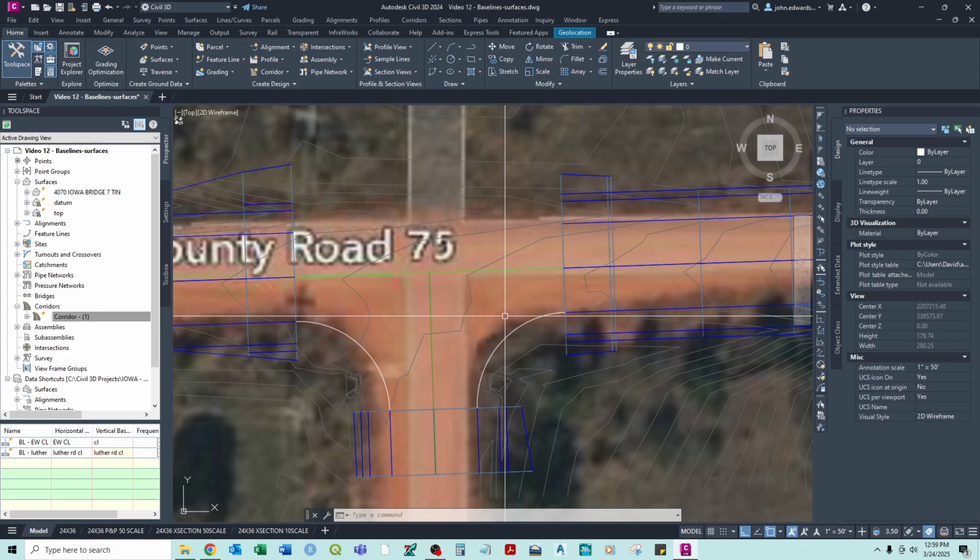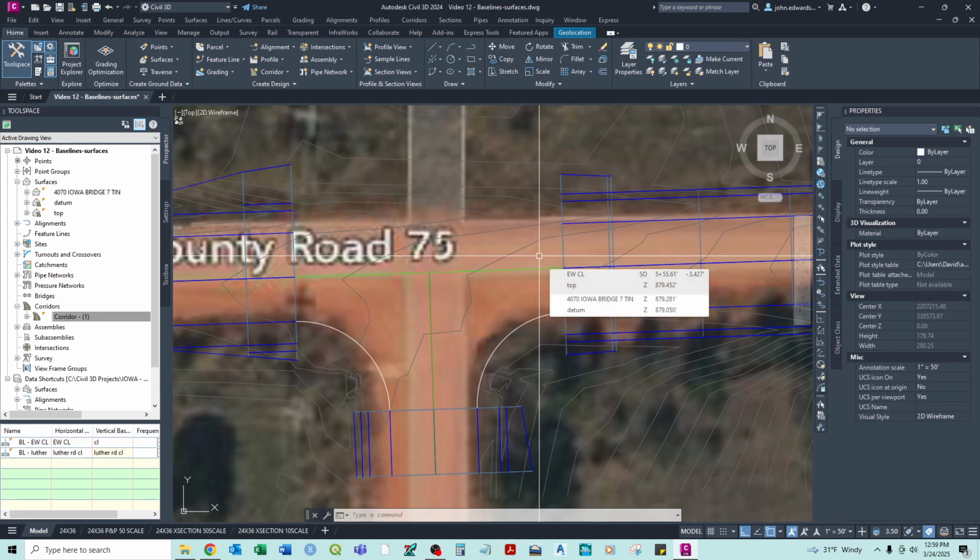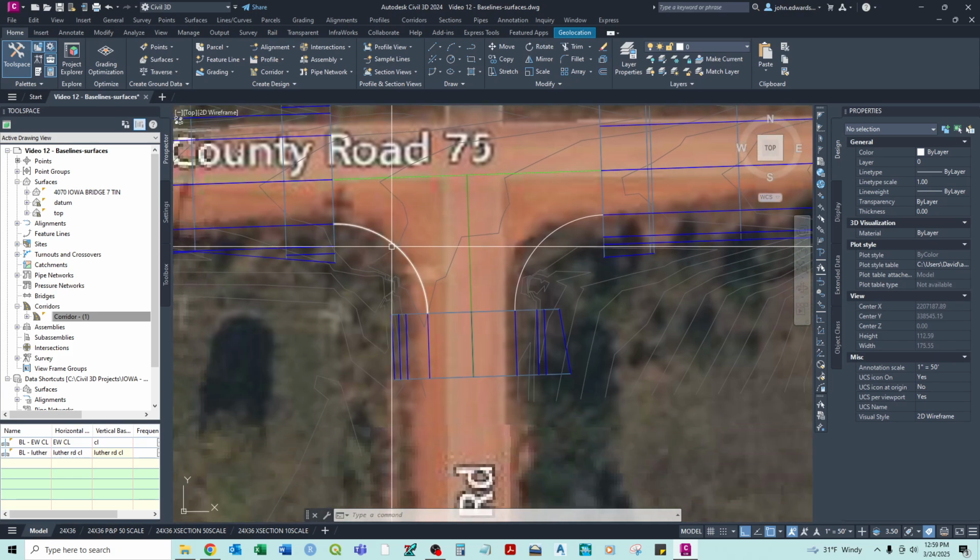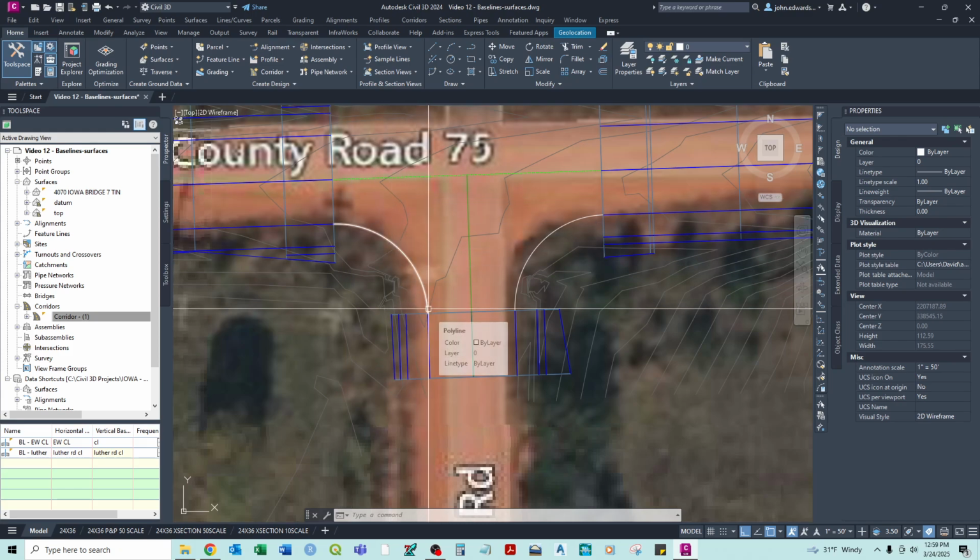Okay, but now we need to create actually a few new assemblies. So let's think about what we're going to be working with here and what assemblies we could do. So this north side has nothing to do with this intersection. So it needs to continue being just its regular self based on the assembly. Whereas here, we're going to need the daylights and everything outside of the lanes, but then the lane is going to have to snap to these two features while going around this feature.